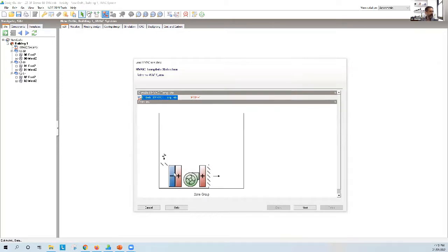There'll be a cooling coil and a heating coil, which will typically both be running on a refrigerant cycle. And then there'll be an electric defrost coil, which of course in Delhi you won't need because we never get to temperatures much below zero and the coils don't generally freeze. Okay.